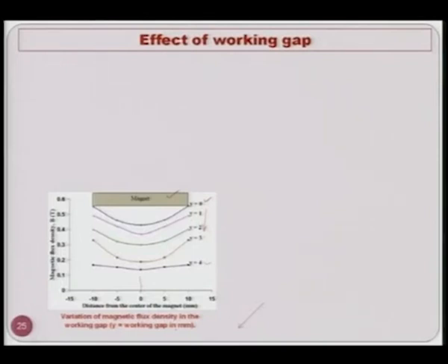This is a very important point, because when the ribbon is being formed and there is a certain gap between the ribbon and the workpiece, and once squeezing starts taking place, that gap is still there with reference to the magnet. So, the thickness of the ribbon will also decide how strong the chains that are being formed are.